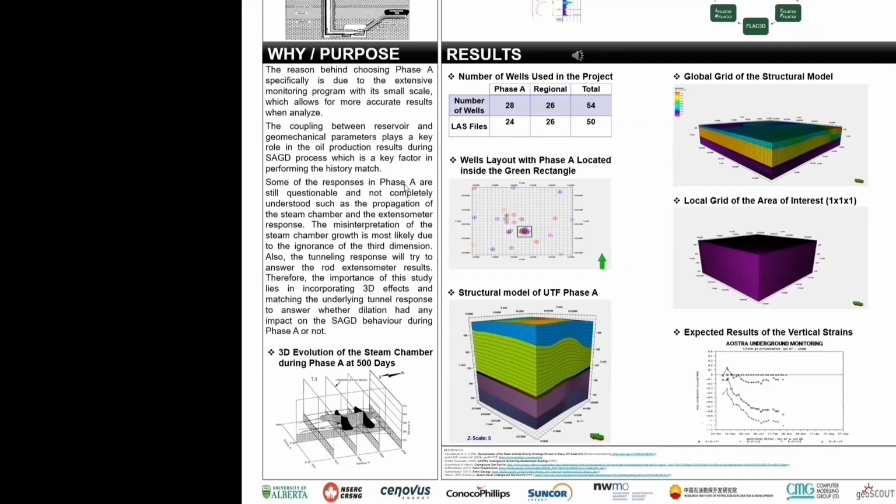So also the coupling will show the interaction between reservoir and geomechanical parameters, which is a key factor in performing the history match, as SAGD is a coupled problem.